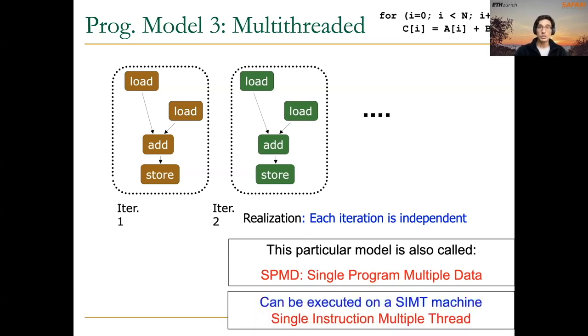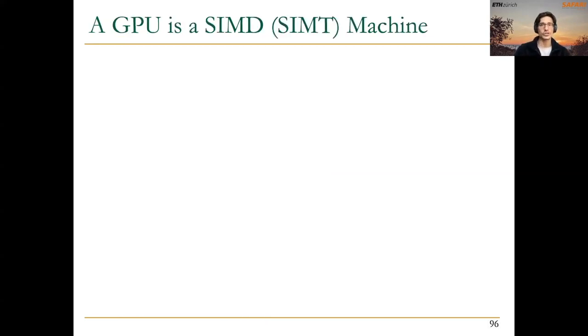And that's why in the GPU context or terminology, we also call this single instruction multiple thread, because instead of writing with the idea of vector processor SIMD instructions in mind, we write code for threads, but these threads, as you will see, are going to be put together in some way in vector units or SIMD units to do the execution of single instructions.